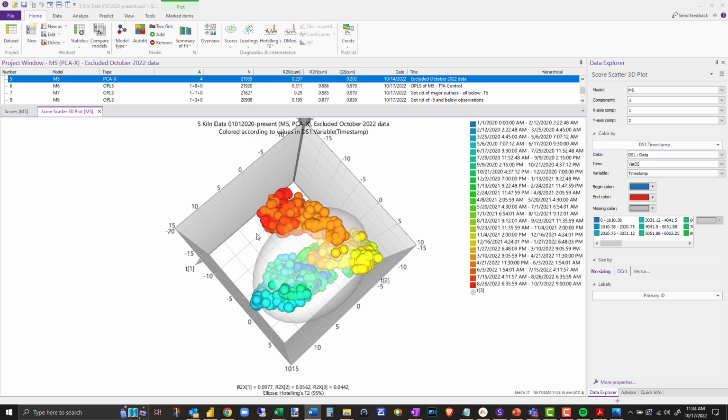What do you mean? I said, well, if you add some caustic at the top of the tank, how long does it take for the whole tank to realize that you added some caustic at the top? Oh, that's going to take like 10, 15 minutes. And I said, okay, so let's go with 10. So 10 minutes is the largest, fastest transient you think you need to capture.